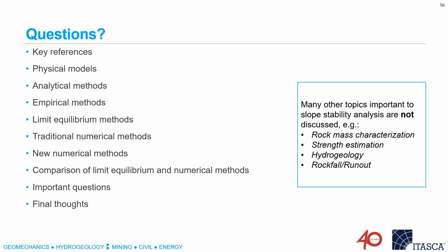We also see it, by the way, in 2D analyses, because 2D analyses tend to be very deep, particularly with large safety factors, and those things probably are just not realistic. But we get shallower failure surfaces in 3D analyses, and when the rock mass material is more frictionally dominant than cohesionally dominant.